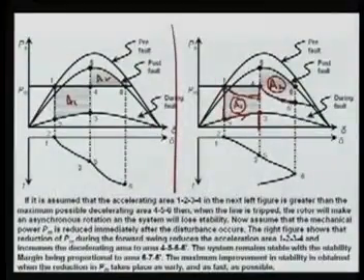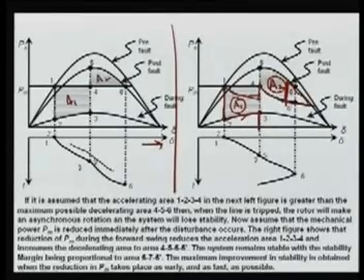It means you can have more margin, even though the system is cleared before, and your system will be stable, meaning you will have more margin here. So you can see here delta, which kept on increasing beyond this 0.6, but here at this point your delta is going back, and we can say here your delta is stable. So this is your delta with reference to the time. So we can see with the help of this fast acting valve, meaning rapid closing and opening of the steam valves, we can again improve the transient stability of the system.